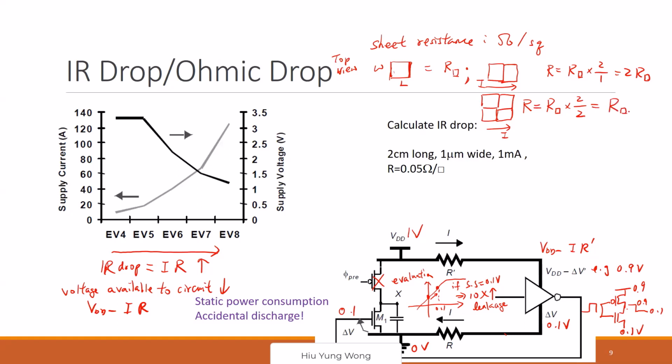Okay, so sheet resistance is something you always use to communicate with the circuit designer, because for them, all they can do is just arrange the width and length. They cannot change the value. For different layers, they can have different sheet resistance, right? For the metal layer, they have smaller sheet resistance. For the diffusion, they are larger, right?